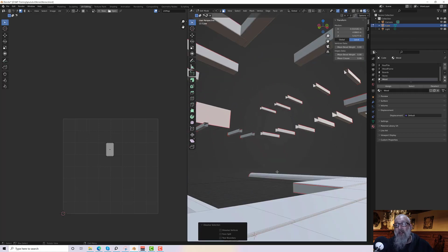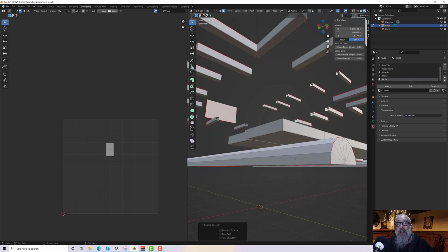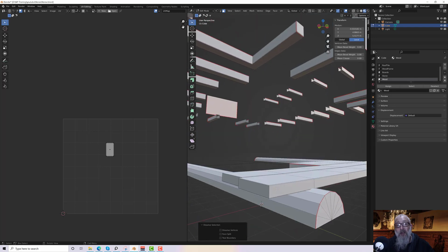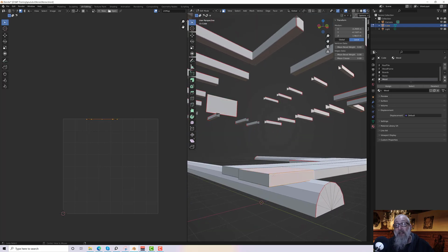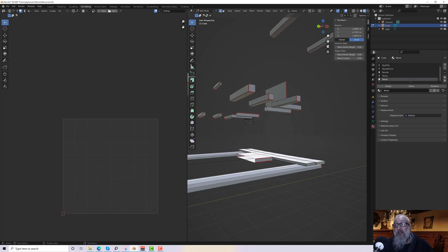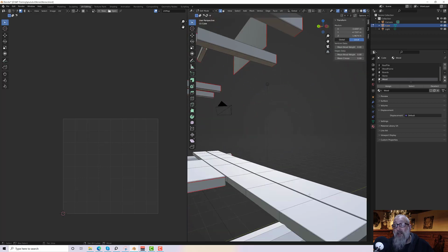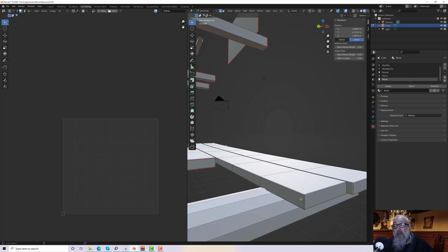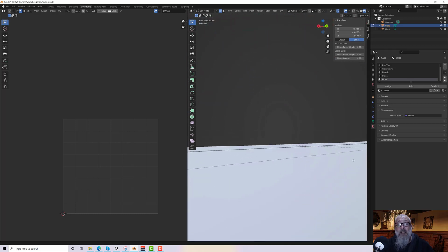See, these logs at the front, or these planks, I haven't defined them, so let's do those. So if I just pop a seam in, just cut the ends off rather, so Alt and click, and then Shift Alt and click there, and same at the other end.